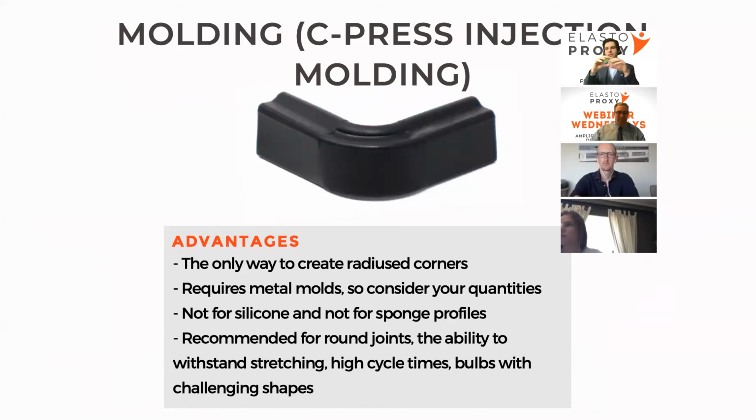They're limited in the radius that they can be bent. So if the radius is extremely tight, but you require a gasket to go over it, the only way to do it is to use a molded corner like that. Again, it could be rounded, it could even be a 45 or a different shape. So that's the advantage of using a molded press.